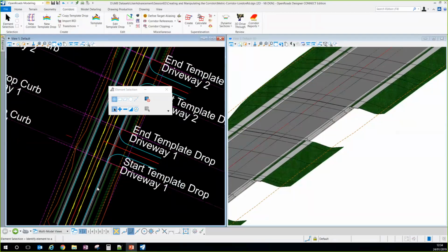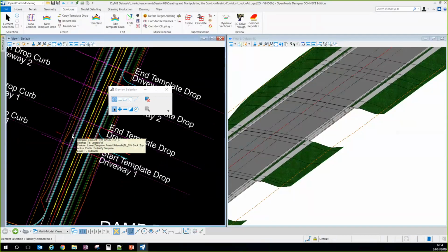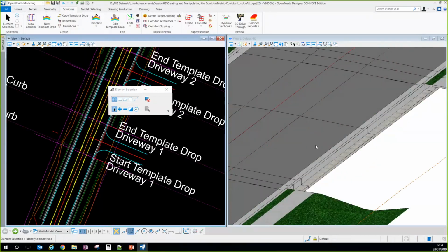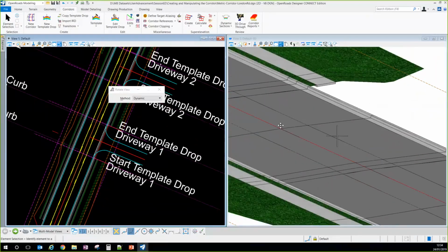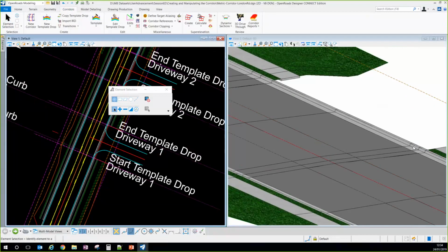And now what I wanted to show you are the parametric constraints. We will use them here for the curbs because we kept them for the driveways. Let me rotate the view so we can see better. Okay. So here we have our curbs in full height, and we want it to drop until 3 centimeters. In our template, if I edit it,